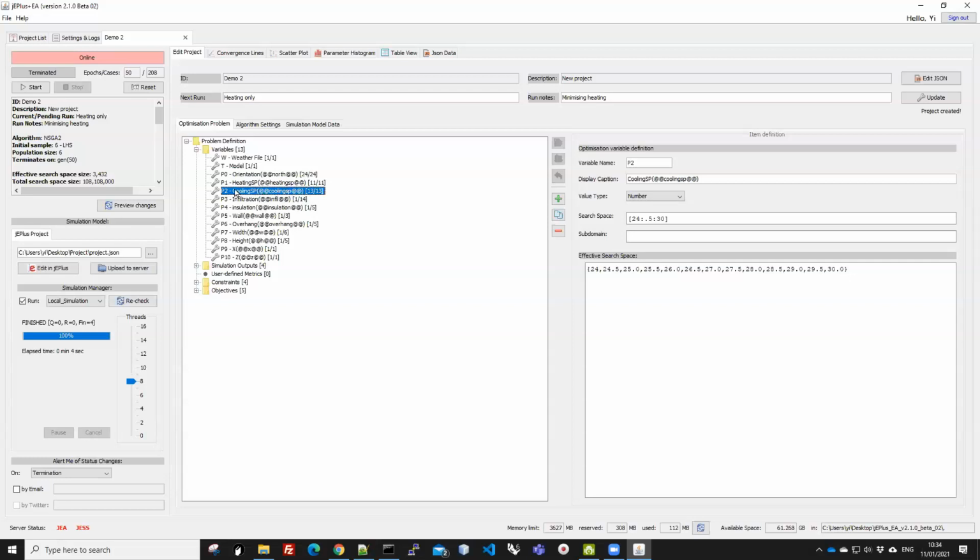I'd say it's almost completely right, because actually the heating set point has no part in the outcome, because it doesn't affect how much heating consumption there is. Whatever the cooling set point is, as long as the heating set point has been set to the lowest, that is 18, and the orientation is facing due south, then you should get the lowest heating consumption.